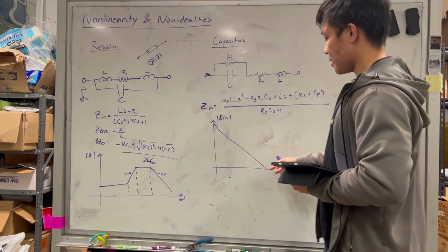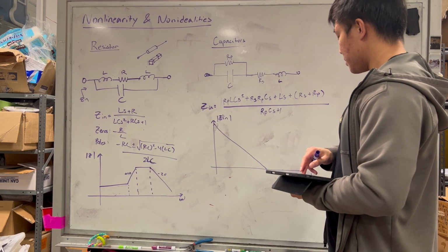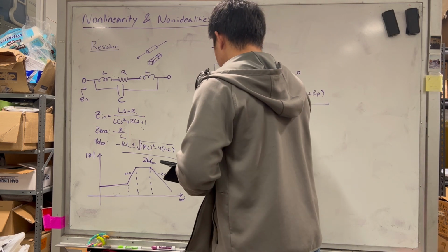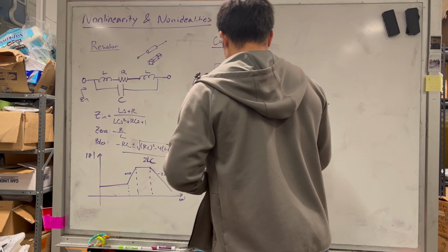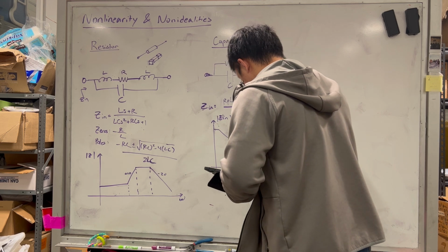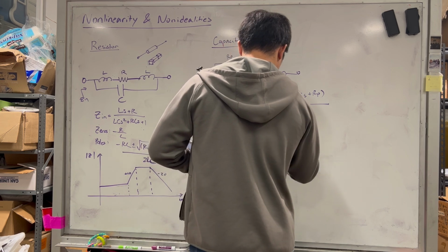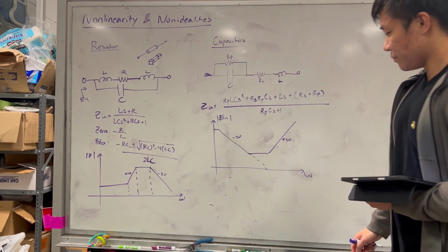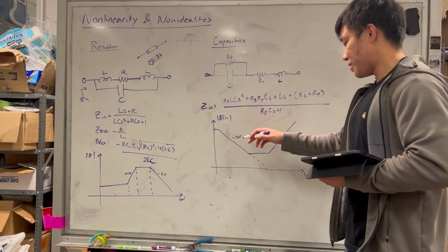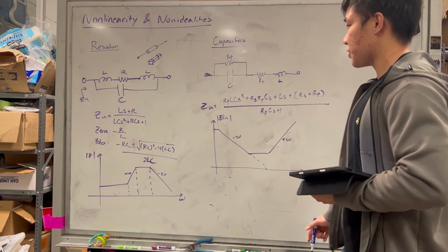So we first encounter the pole, and the first pole is actually very close to DC. And what you actually see is you eventually hit some resonating point, you hit a zero, and you hit another zero like that. So depending on how close these poles are, you can either see a really big dip, or you can see some type of flat region for your transfer function characteristics.